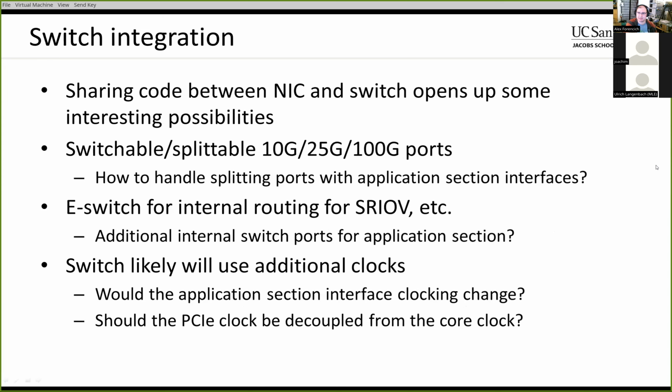Right, so that's that. And then also the switch integration, as Carlos has been working on putting together the packet switch design. If we're going to integrate that into Corundum on some level, there are some questions in terms of how that's going to be exposed at the application section interface level and with the internal switch ports. There's also a clocking consideration there. It might make sense to decouple Corundum from the PCIe clocks so we can run it synchronous with the switch clock.